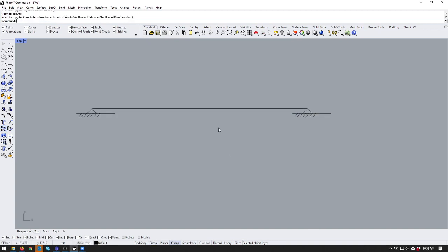Karamba is an engineering tool, and so the system wants to use engineers' units. So typically, I will open up a Rhino model, and I will set that Rhino model to be in millimeters as I open it. Or if I open up a Revit model, that Revit model is going to be in millimeters when you pick the international units option for that one. But if you remember back to literally the first tutorial, engineers work in meters when they work in international standard. So Karamba is also going to work in meters, which is a little bit contradictory because there are some parts of it that don't want to work in meters, but we'll talk about them in a moment. But the main engine works in meters.